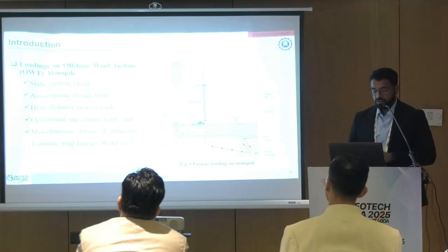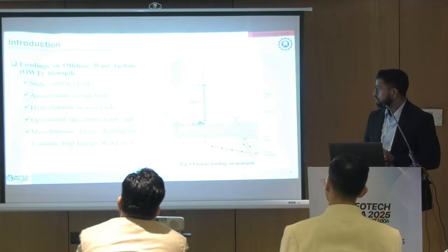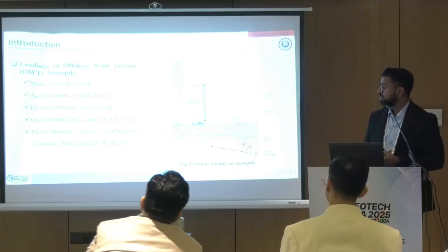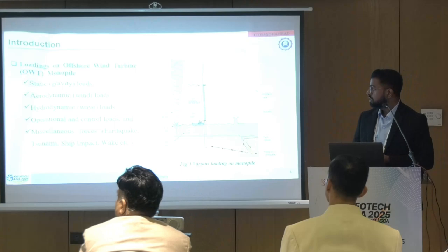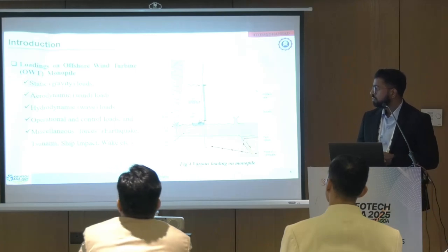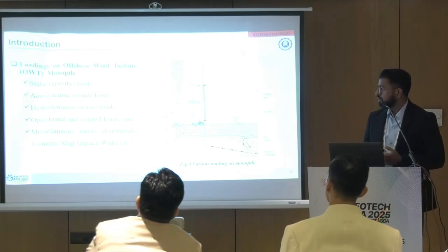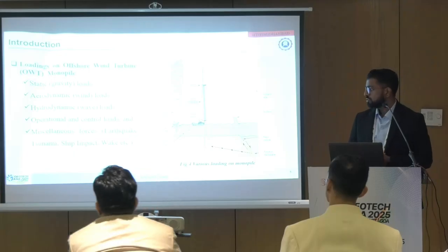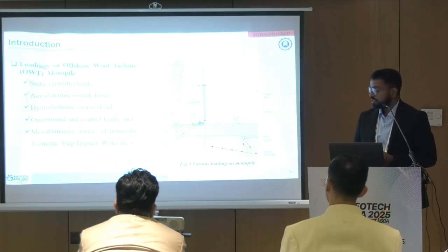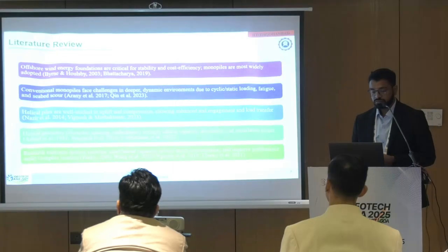Loadings on offshore wind turbines are static loading, which is self-weight, aerodynamic, that is wind load, hydrodynamic, and operation and control loading. While we install, there is an impact load as well. And miscellaneous forces are like earthquake, tsunami, wake, and sometimes ship impact.